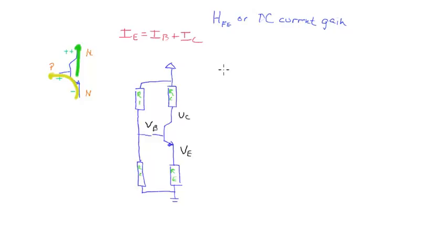So what is the voltage at the base? Well, this is just a voltage divider. Let's say that this is some arbitrary voltage, Vs, voltage from the source, and the voltage at the base then is a diode drop above the voltage at the emitter. So for the purposes of this explanation, I'm going to place this emitter at ground, which will just make it easier to do our calculations.